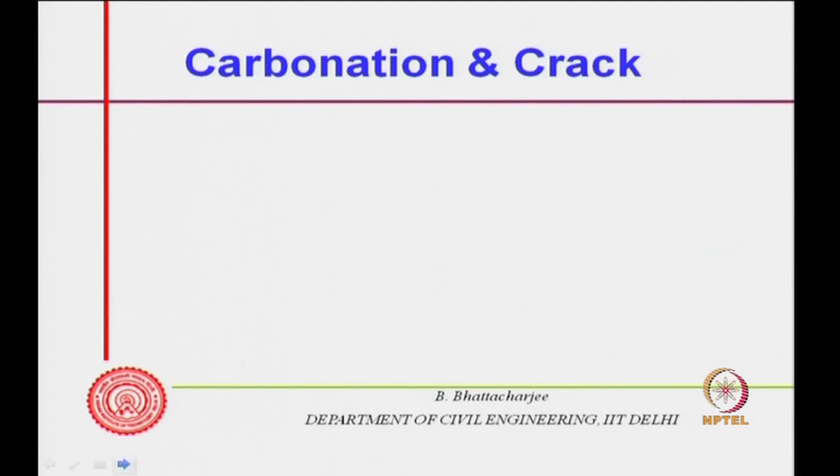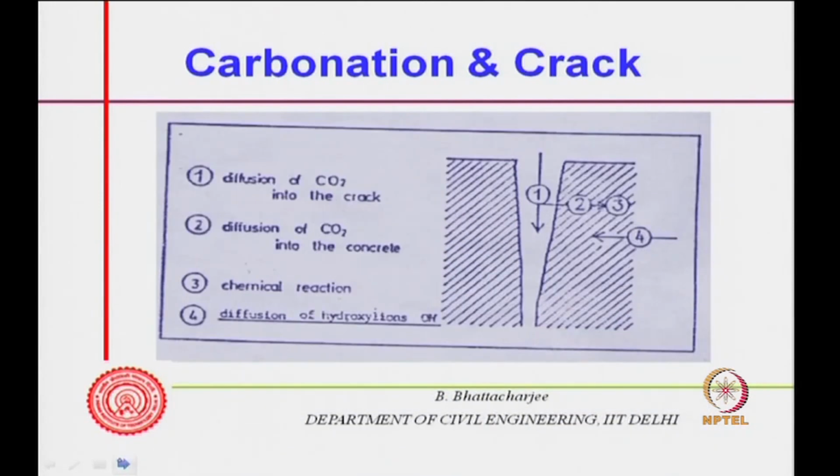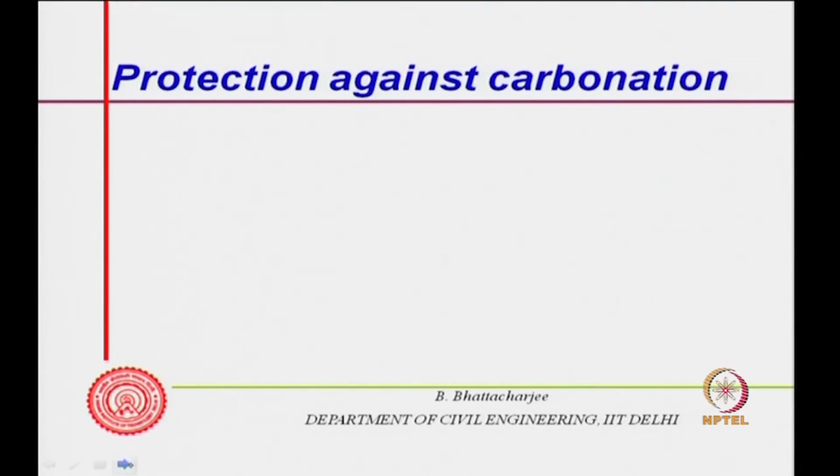So, what is important for us to understand is that carbonation progresses in steps, and it depends upon the wetting and drying cycle, right. This is a simple model for a specific condition; actual conditions should be modeled under wetting and drying. If you have a crack, carbonation can penetrate along this direction, with diffusion of carbon dioxide first into the crack and then inside. So, in cracked concrete, the carbonation front might reach in this manner. If you have rebar somewhere there, then there is a problem.